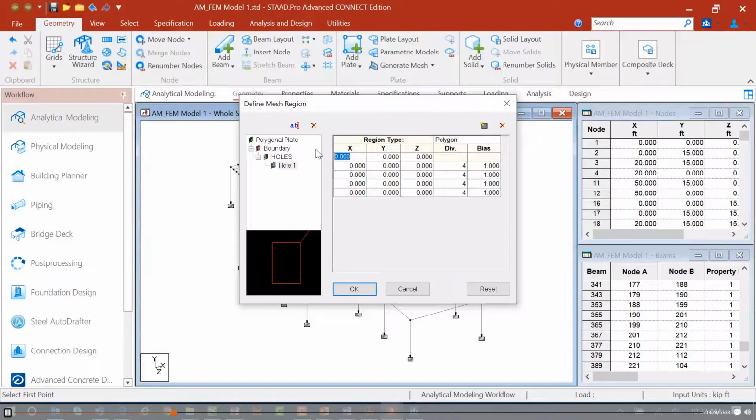I'm going to start with my starting node. Here I'm going to enter 13, 15, and 22. So what is important to note is that these are using global axis coordinates, so you will have to know or think about this a little bit before you get to this step of where you are in space, okay? So I'm going to enter my first node, and then I can add additional rows as needed for the rest of my geometry. What you're going to notice is I do have some lines starting over in this area. That kind of gives me a good idea where I am in space.